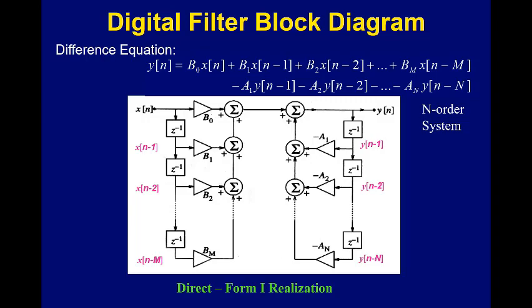So we can literally term by term find the term in the difference equation, find the blocks of hardware that implement those particular terms. So there's no additional, no simplifying, no rearranging, just explicitly implementing the difference equation exactly as it's written. Now you go on to take 419, we'll show you some different ways to simplify that or other alternative ways to implement it that are way more efficient, but this is the most basic implementation.